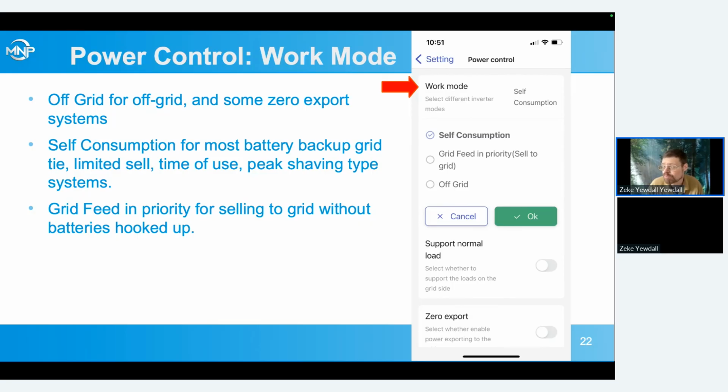And it's basically prepped for adding batteries in the future. It can also be used for net metered systems, but it has some problems with the state of charge of the batteries and state of charge drifting, which are better addressed by setting it to self-consumption with a reserve capacity at, say, 96%.